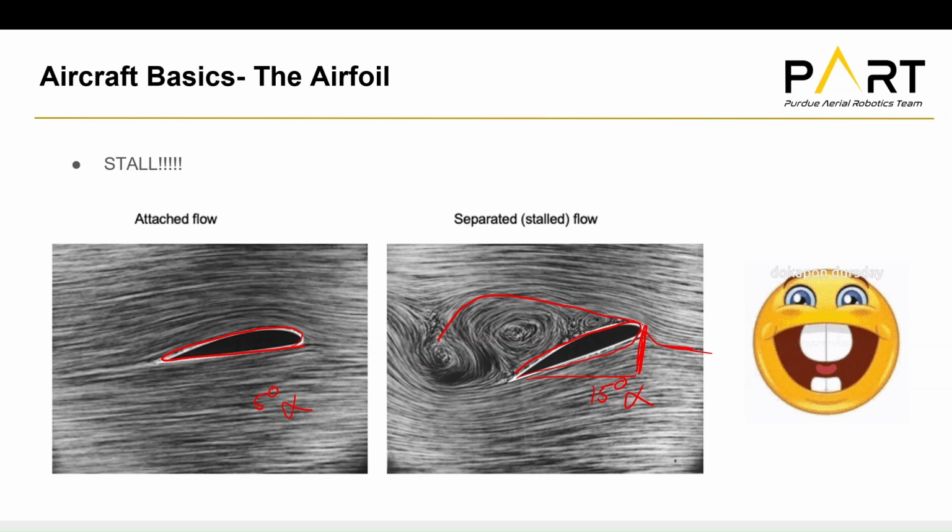So now all your airflow is hitting this giant surface area and overshooting it, creating these vortices in the middle, which are not good. You do not want turbulent vortices. This ruins the pressure differential because now you have this very energized, higher pressure, stalled out air on top of the wing that kills your lift. And this is where you see planes fall out of the sky.